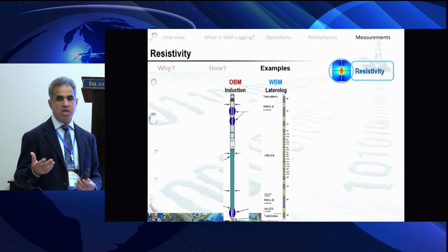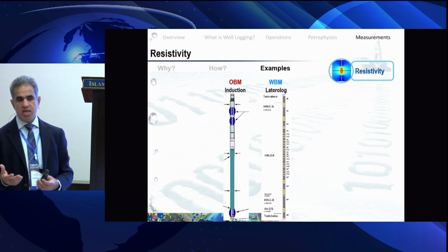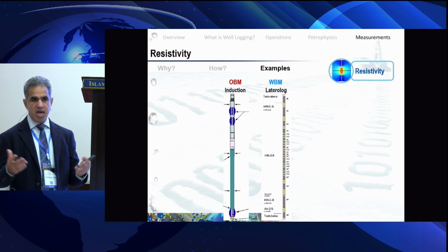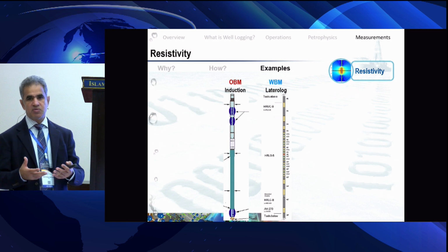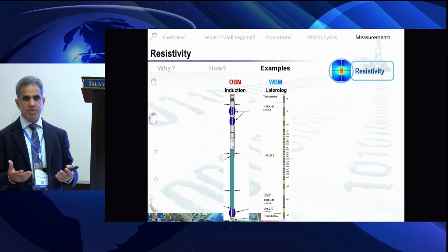are not stable to drill. They create problems. They basically cave or they swell. So they are not easy to drill with water-based mud, so oil and gas companies drill them with oil-based mud. It's very expensive, but this is the drilling challenge they have to tackle. So they use oil. Oil is basically diesel.